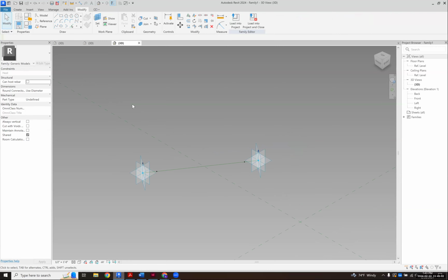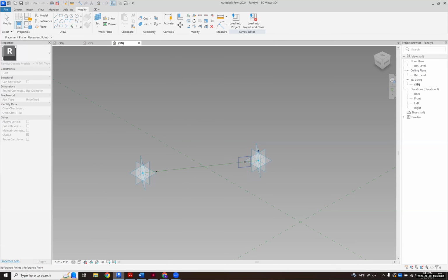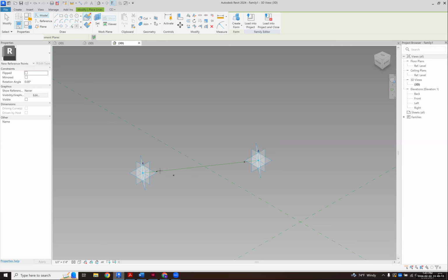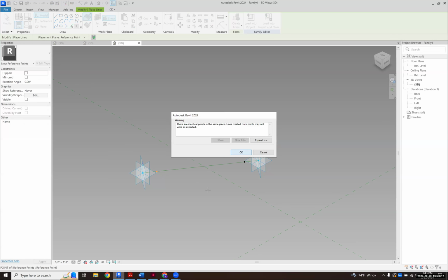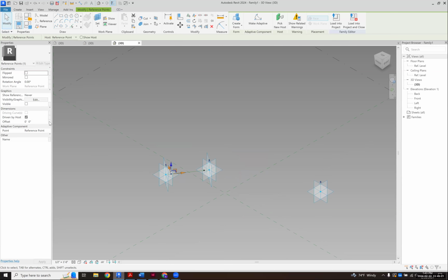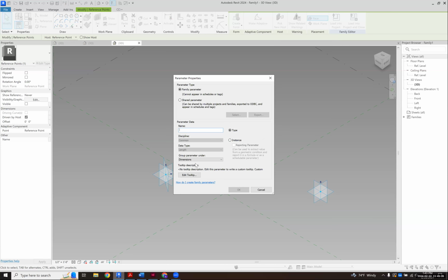Now I'm going to do the same thing I did in the thing that we're not talking about, and I'm going to grab a point. I'm going to go SW, tab, grab that one and drop it on. Okay. I'm projecting out from here. I'm going to just make a new parameter and call it cantilever. Remember, this was let's call it extension. And it's an instance.